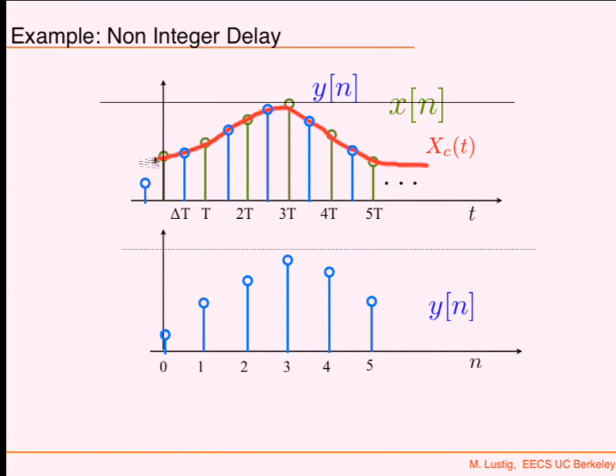The signal continues on. It's like a continuous thing. Does this make sense? So now, that's a great system. So when I do this e^(jωΔ), where Δ is not an integer, it's as if I reconstructed a band-limited signal, shifted it by some ΔT, and then resampled it. That is the equivalent. It might not be originally continuous, but that is the equivalent in terms of a continuous time. Yes?